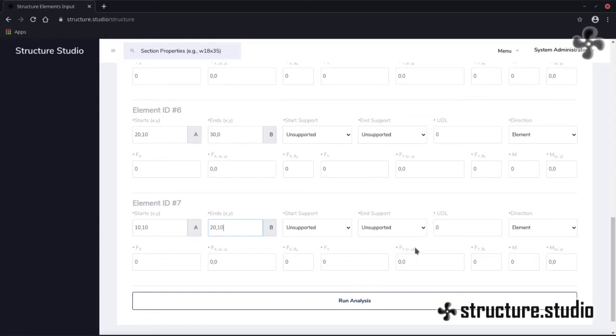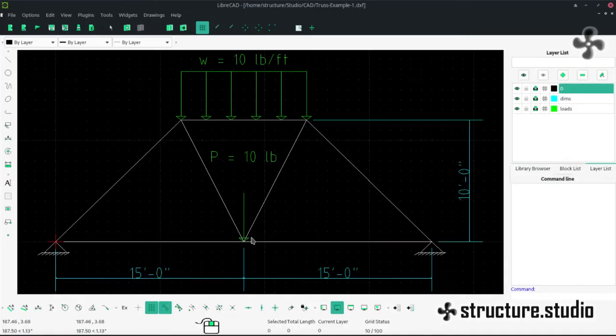You can leave the load until after you're done and then add it. Like here, adding 10. I'm gonna look for the point load. With a point load, you have multiple options where you can enter it. It doesn't matter. What really matters is this node has to be defined before you add the load to it.